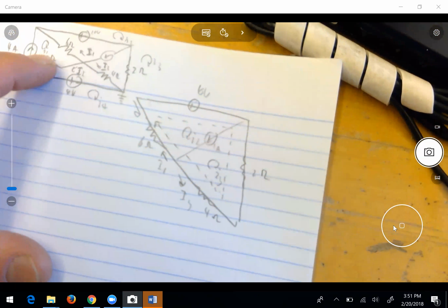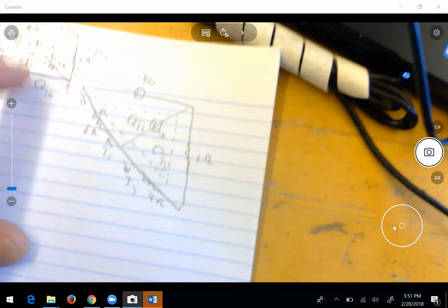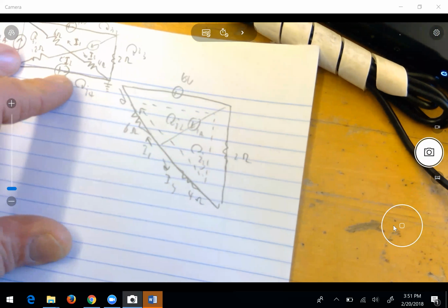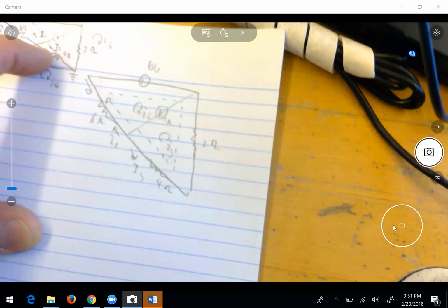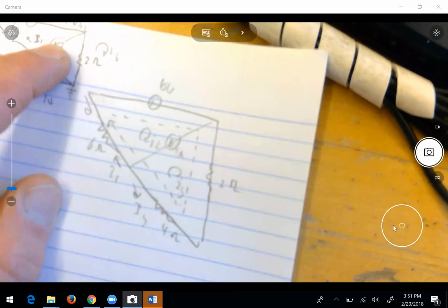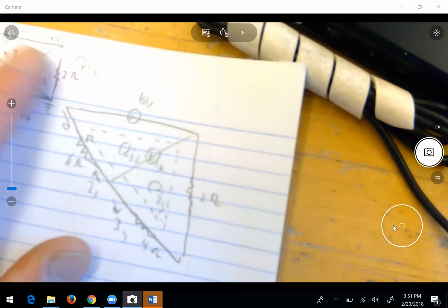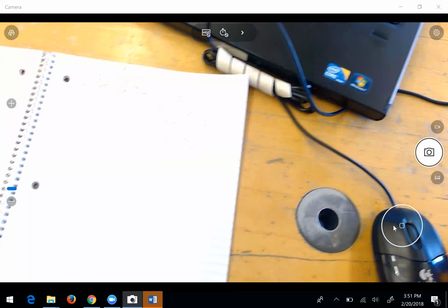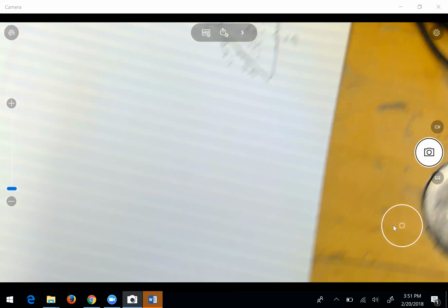Oh, right, it's the only current going through the outer branch. The other ones are unknown. I4, that's a voltage source, so you don't know that. I1, my bad. But this one, I3, I1 minus I3 equals whatever that is, 1 amp. So it's just drawn funny. This one was pretty busy too.